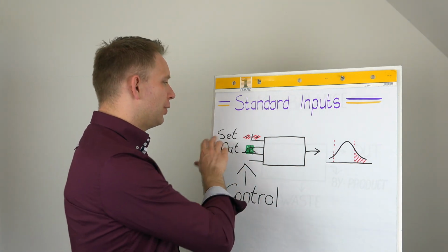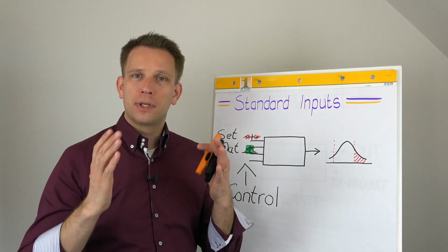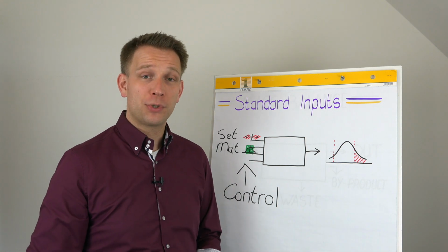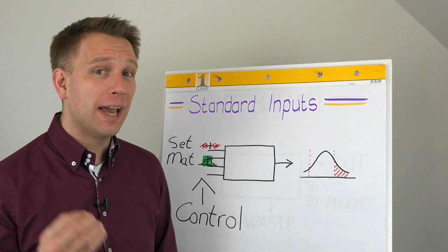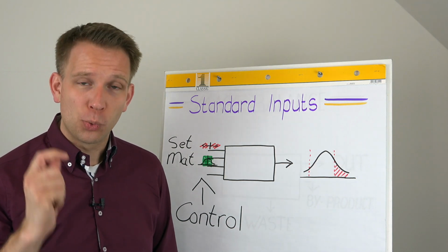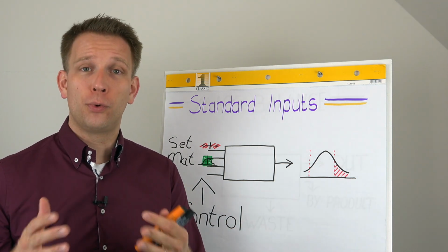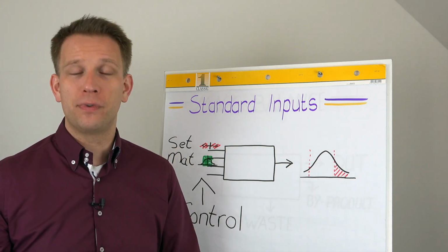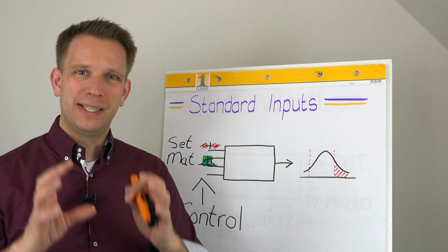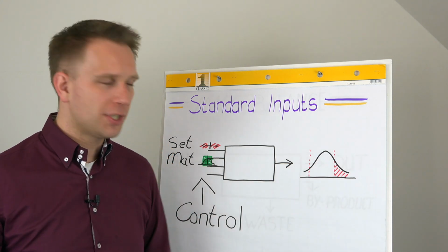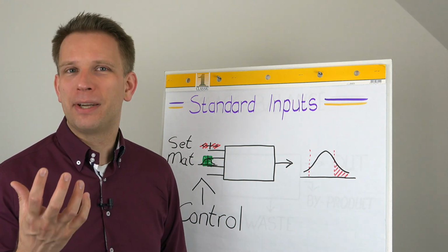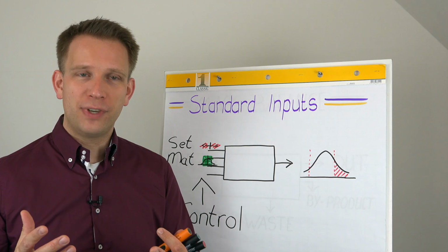So make sure that you check if machines are set to all the parameters that we defined in our standard operating procedures. And by the way, if you do not have a standard setting in your operating procedures, there is work to be done. Work for technologists, for process improvers, for management, for anyone who understands this line and can tell the rest of us what should the set point be. So that's also immediately a bit of homework that you can take to your own factory.